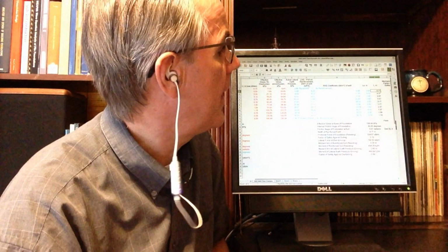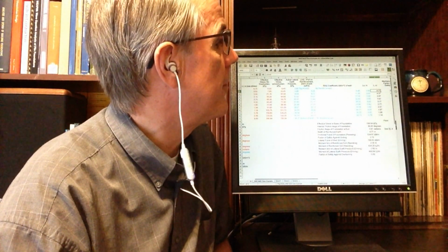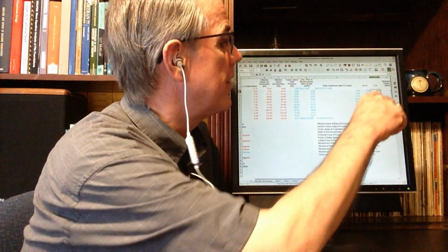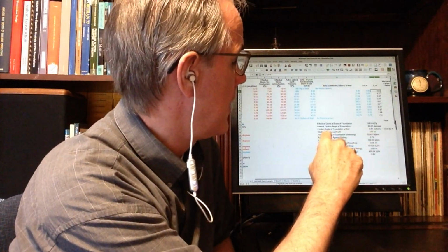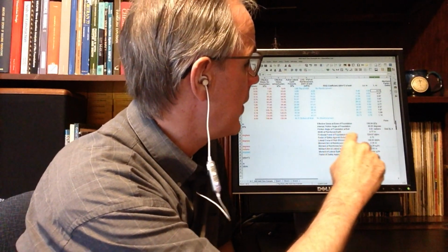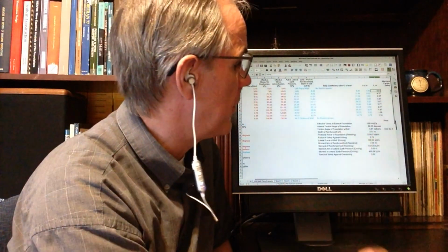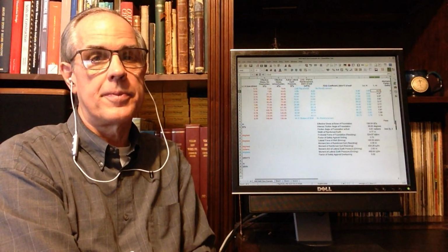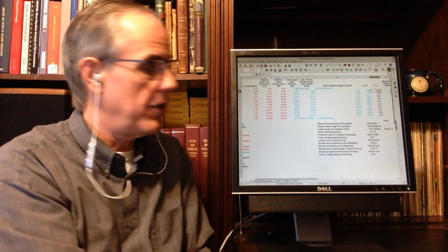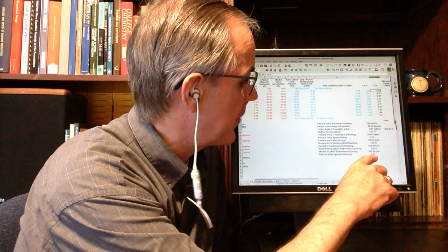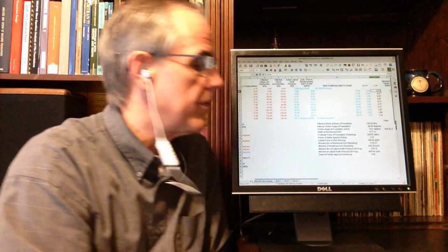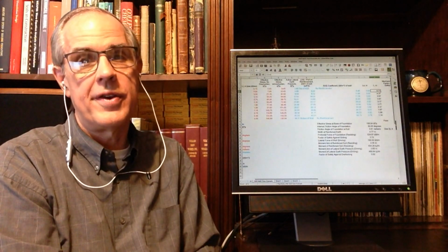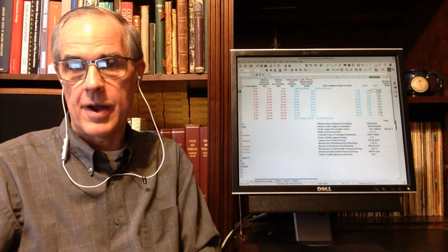So with that in mind, we're going to assume that 4.77 is the largest, and so the width of the reinforced earth is that, and we'll do our calculations. Even at that, you'll notice that the factor of safety against overturning is less than unity, and I'm going to talk about how to fix that problem in just a minute.